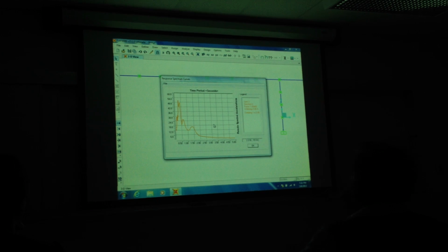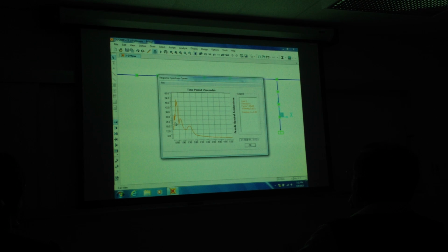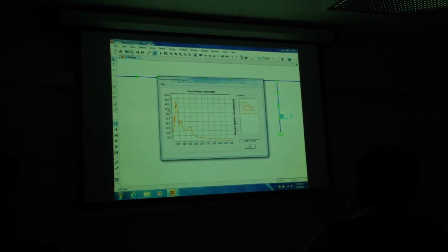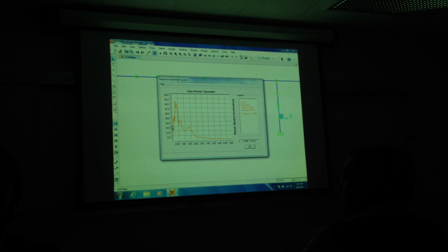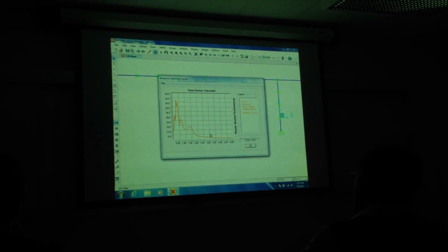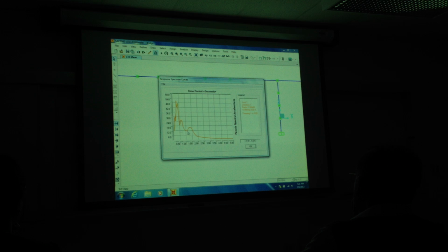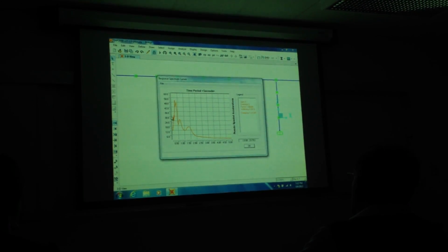So that's what our actual ARS curve looks like for this earthquake. If you remember, this is actually feet per second squared here, it's not in G, so let's keep that in mind. And if you remember before, I had it go up, go over, go down, and then over, right? The idea is that if this is one spectral plot, if you generate other ones, you'd have other curves that look different from each other but with an overall similar trend, and then the envelope goes over all of those. For design purposes, it's like we've looked at all the possible earthquake motions.